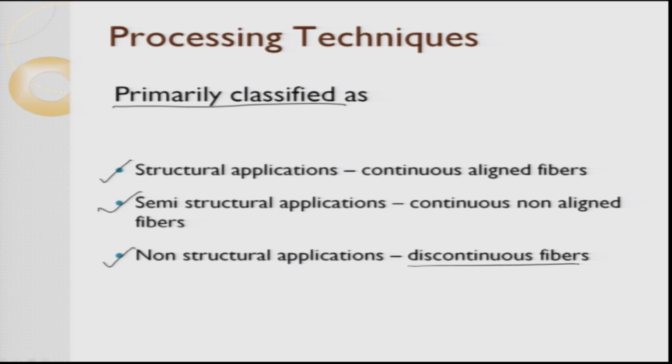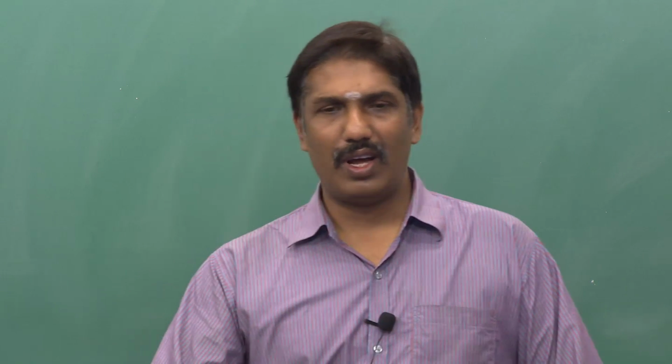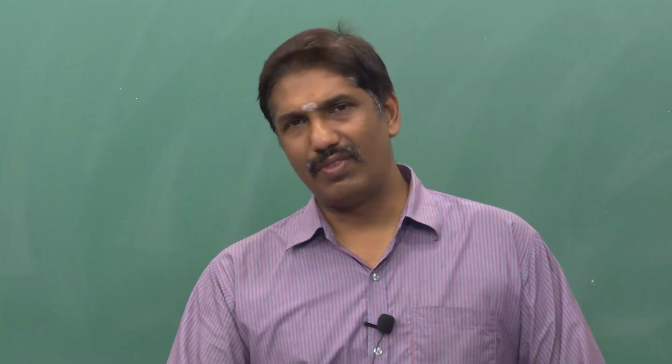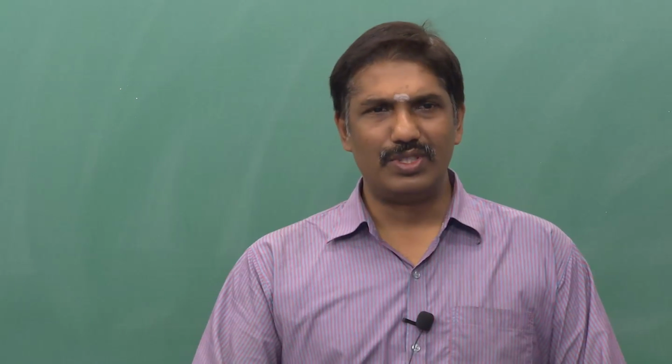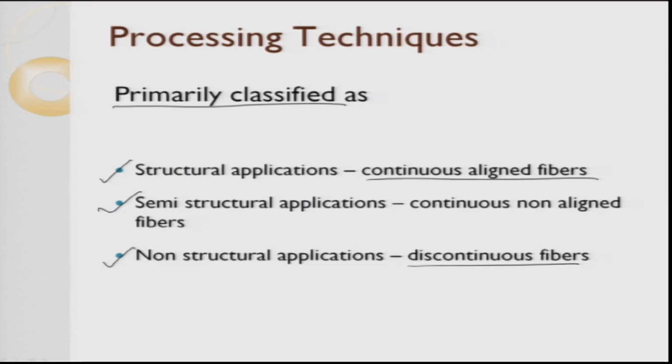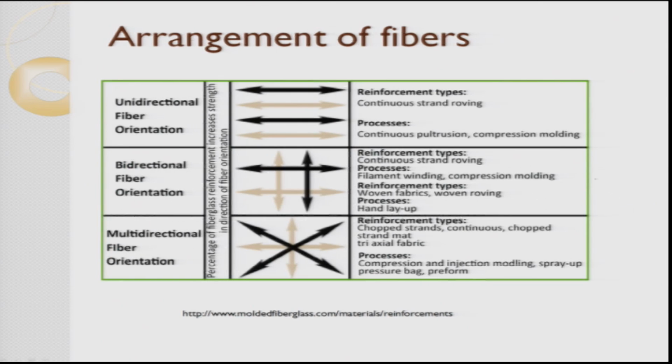Discontinuous fibers can be like you take a long fiber, cut it into several small pieces, and then stack them in a non-aligned fashion or in an aligned fashion to just fill the space. When I talk about structural applications, the fibers are aligned in the loading direction. So, this will give you a major lead to decide which process to choose such that you can meet the customer requirements.